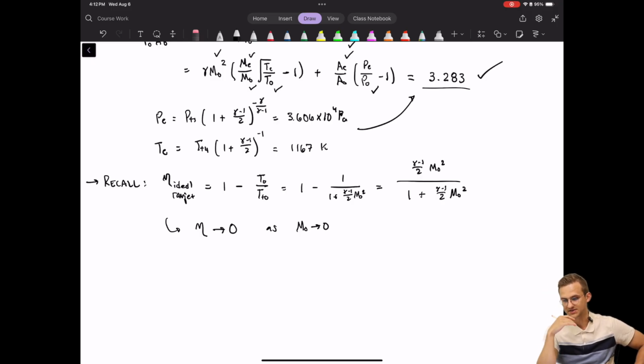It's very flat. And so what that's telling you is that for a low entrance Mach number, your stagnation pressure doesn't change very much throughout that Rayleigh process. At most, it's going to be about 20% or so, because I believe the PT over PT star for a low entrance Mach number is around 1.2. That's sort of an ad hoc explanation, but that's what's going on there. You can look at that to rationalize it yourself. But in general, this is why we always assume that the pressure drop across the burner is approximately 0, and that pi b is about 1.